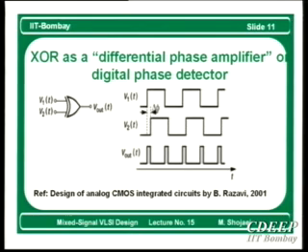That is another interesting point. In the transient duration the frequency changes, but after all, when the phase is established, the frequency settles on the original frequency, which was the reference frequency. That is also a good point. If you have two frequencies, they are already the same, but there is a large phase shift. The frequency will change, the phase shift will get corrected, and again the frequency will come back to the original frequency. So we will stop here and continue next time.